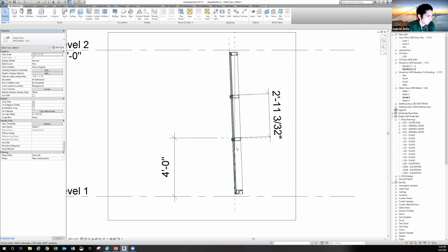Yeah, no, this one we'd have to create another wall. So there'd be another wall that goes from the floor level to the top of it, and that wall will just have the mullions. It would have a caulk joint and it would have the sill track. And then in between, we just have an empty glass unit. That's just to show the caulk joint and to get that sill track in there. But because we can't nest roofs into roofs or have a wall that's sloped, that's our workaround that we've come up with.